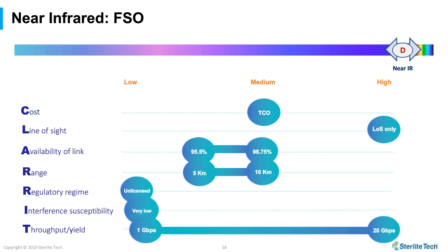Real quick overview here. FSO has its limitations. While it has a lot of advantages, there's gigahertz, in fact, terahertz of spectrum. You can actually get a lot of bandwidth out of it. It is also susceptible to atmospheric scintillations, fog, dust storm, etc. So it puts the availability at a disadvantage, but you can also design the network such that you compensate for that by modifying the distance or the throughput required. So as I said, you have levers to play with to adjust, and also useful use cases where you absolutely have nothing else, and in fact you have no spectrum.